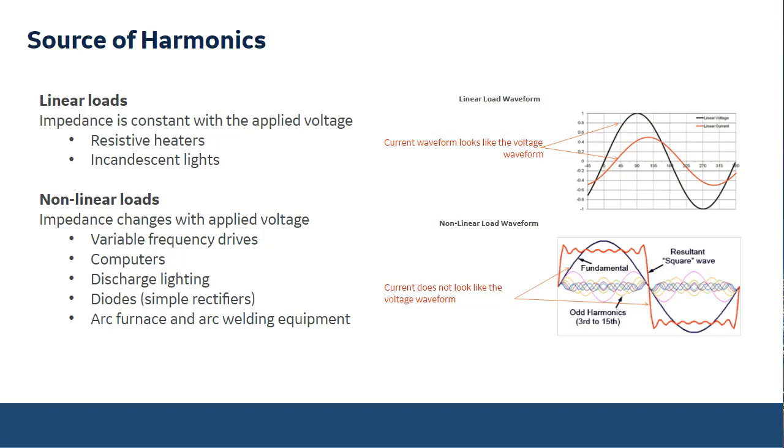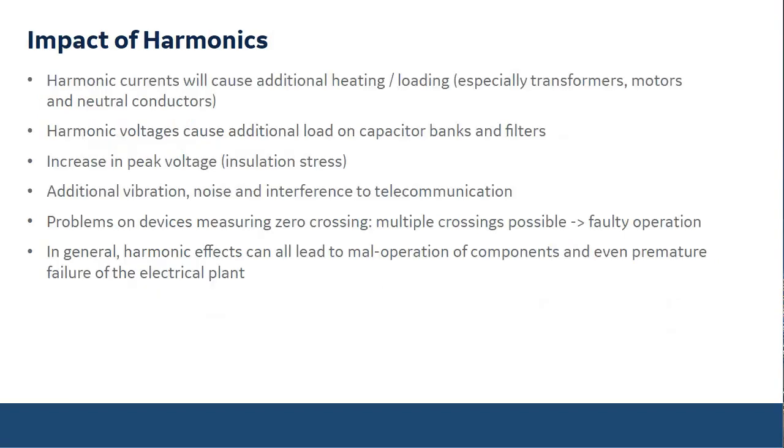Then the impact of harmonics, what will these cause? They will cause additional heating and loading, especially in transformers. They will cause additional load to the capacitor banks, what we are now talking about. They will increase the voltage stress on capacitors and also the current and voltage stress on the reactors and everything. Those were the ones related to capacitor banks. They will increase the peak voltages, so they will cause insulation stress,